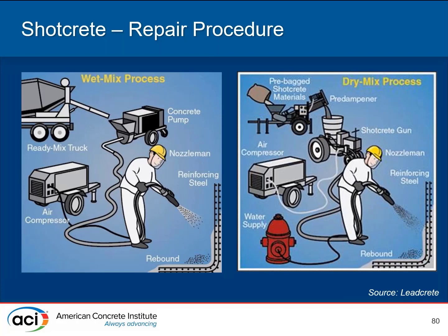The difference between the two is you just mix your pre-bag material. Essentially it's going through your gun dry until right at the end where you're adding the water. The nozzleman adds the water as they go. One of the challenges of this is that you're relying on your nozzleman to control the amount of water in your shotcrete. So it does rely on an experienced nozzleman to get it to be the right consistency.